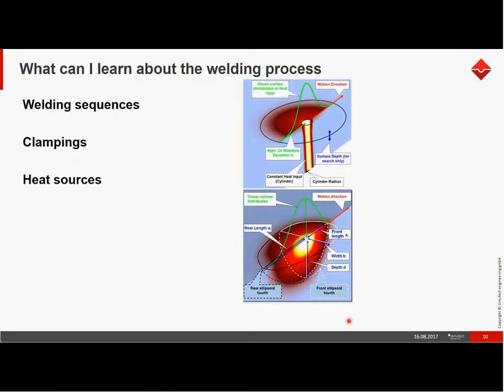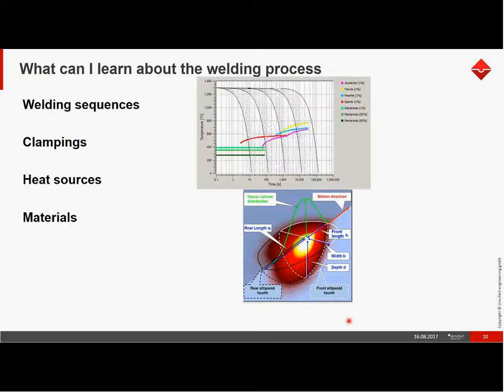You can use different heat sources. For instance, you can also use a heat source to perform something like preheating and look if, for instance, the gap closing or opening will be better, or if stress is distributed more properly.